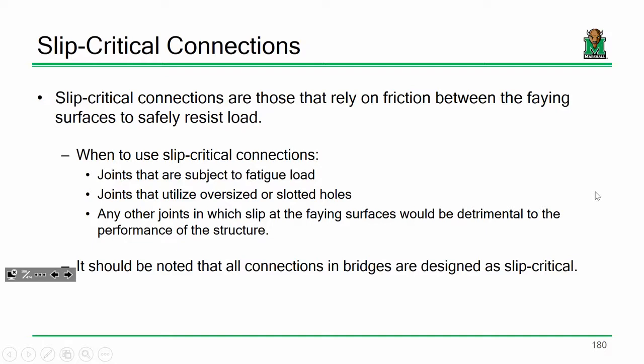It vibrates off, right? Over time, that bolt is just going to get loose, and it's going to screw off. Now, what we're talking about are connections that are holding up large-scale structures. We can't have that happen, right? So in a structure where we have fatigue considerations, we're going to use slip-critical bolts.